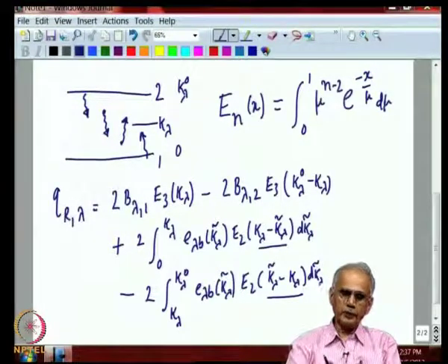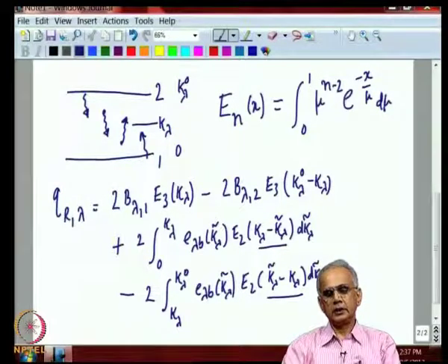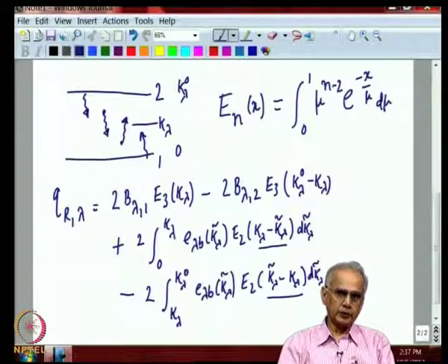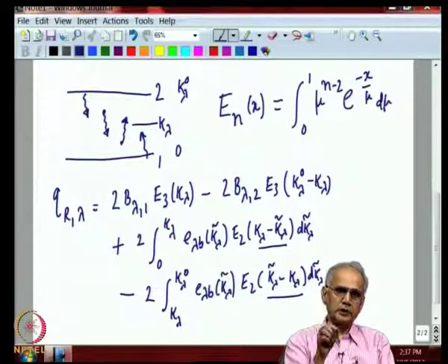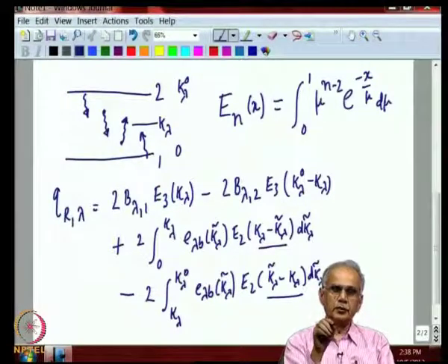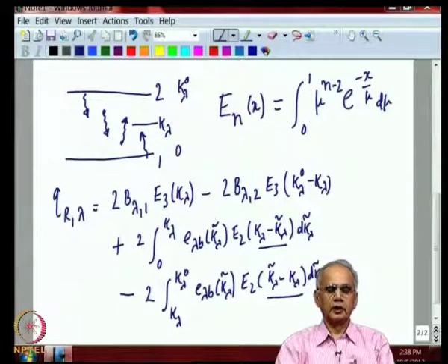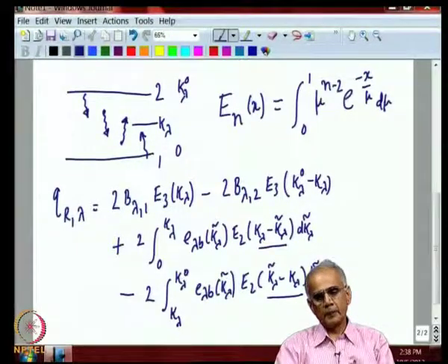And the key point here to remember is that because in this equation we have an integral equation, essentially what you see here in radiation is something very different from either conduction or convection. Conduction and convection are governed by differential equations, so that the temperature of a given region is influenced only by the temperature of the surrounding regions, immediate surrounding regions, and that is why we are able to write everything in terms of derivatives in differential equations.